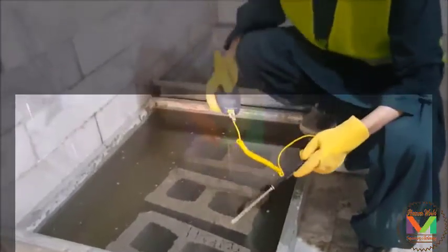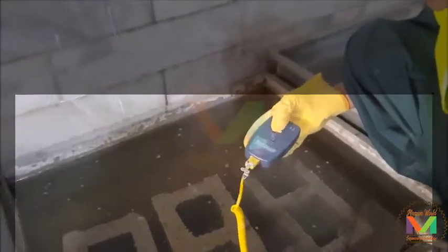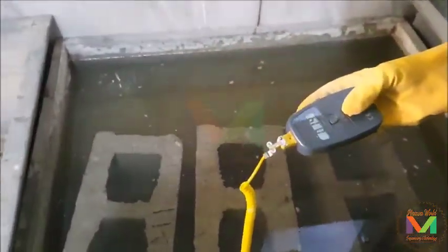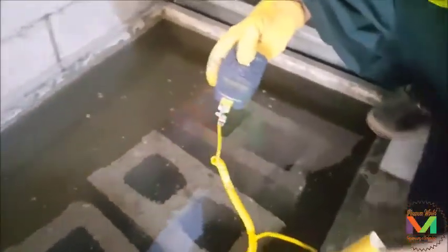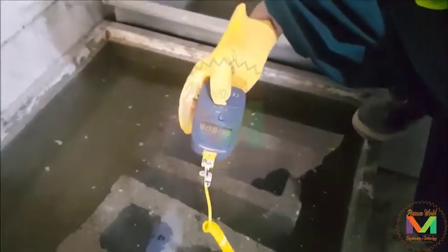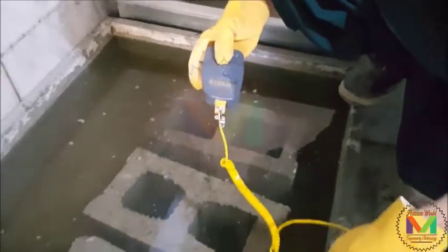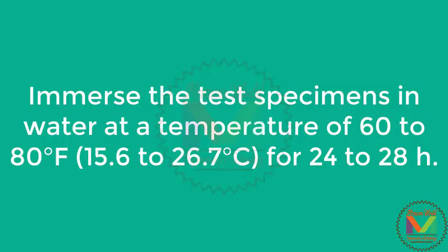Now I'm going to indicate its temperature according to ASTM, which is 18 Celsius. These 3 specimens are going to remain in water for 24 to 28 hours. After that, we have to remove these specimens from the curing tank and carry out the absorption procedure.